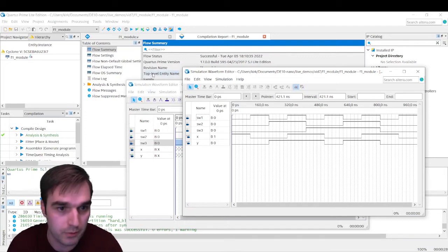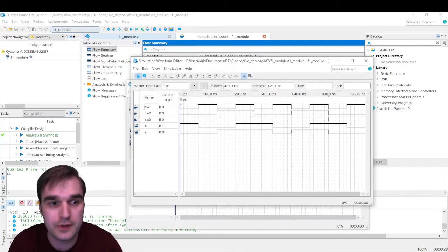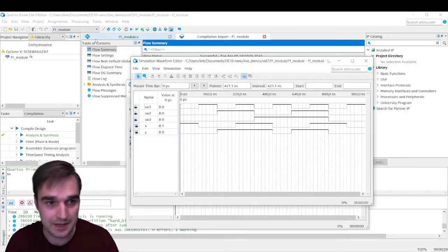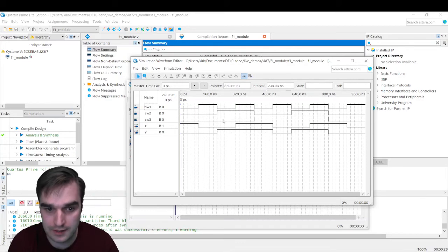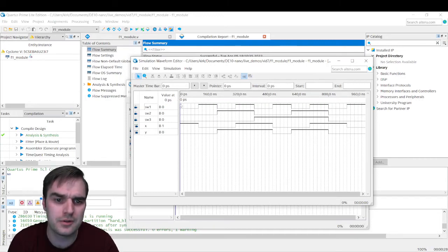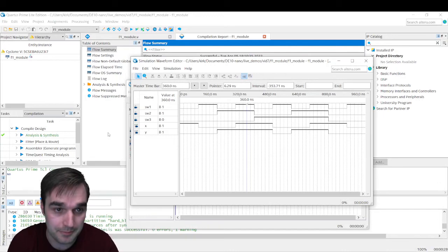So in order to get this waveform, I had to make a new Quartus project and set all that up, then put in a new Verilog file and do the waveform again. Now it works and it looks like it is the exact same as the block diagram. So feel free to not follow along if you were trying to. You don't have to actually go through with this step, but if you want good practice, it's good practice.